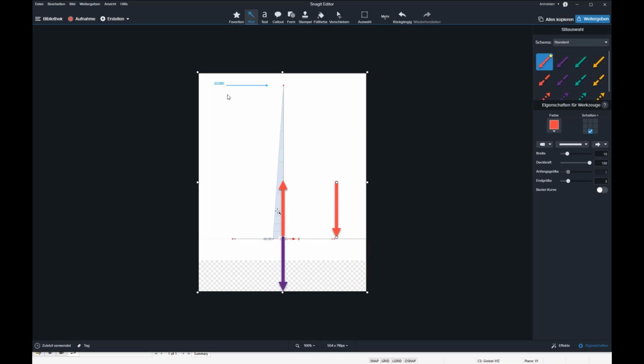If I play with this cantilever or lever arm in between. For this, I draw here a small lever arm in between to get a better view. I change it here like this. And now the question is, how big has this to be? Or this is also not how big, because this is already clear according to the size of the foundation, but it depends how big this bending moment should be to be in equilibrium with this purple arrow.